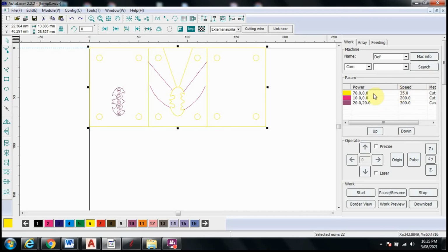So on my laptop, a 3mm MDF is actually my yellow layer, but you'll use the black one on the school laptop. Now again, if you're going to use a school laptop, you are going to have to change these settings to the correct ones. Now the correct settings are given to you in your booklet. There's a little chart there which tells you what settings to put them on and what numbers to change them to.